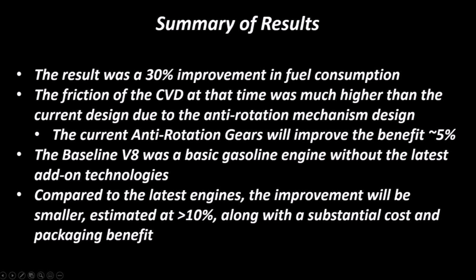Also important to note was the baseline gasoline engine was a basic gasoline engine. It did not have variable valve actuation or cylinder deactivation. It was not downsized with an add-on turbo and intercooler, nor did it have direct injection or a cooled EGR system for dilution. If the cost of the CVD and the baseline V8 were compared, the CVD would be more expensive because of the two sets of roller bearings. However, if it were compared to an engine with all of the aforementioned add-ons, it is estimated it would still be about 10% more efficient and would be far less costly.